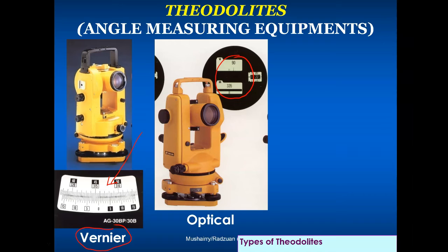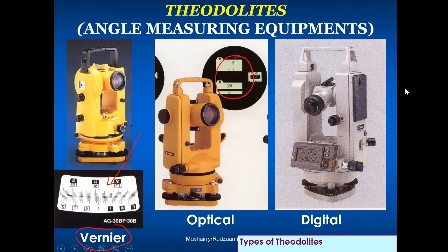It's akin to a micrometer. Like reading a micrometer, but not exactly, something similar. And then obviously now things have gone digital, with advancement in technology, which means that we do now have digital theodolite, simply because angles are now given on a screen, normally an LED screen, that gives you either the vertical angle V or the horizontal angle H.